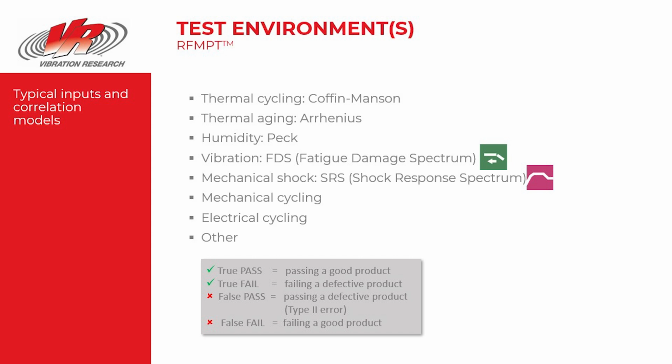Firstly, field correlated models build confidence that identified test failures are probable in the field. They allow you to fix the right things for the right reasons. They are necessary for defining virtual twins or math model boundary conditions. And finally, they establish appropriate test acceleration factors. We want to be certain that our testing only produces true failures and for the right reasons.